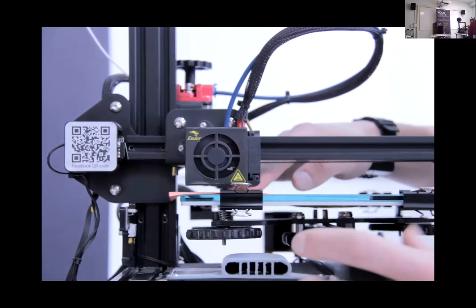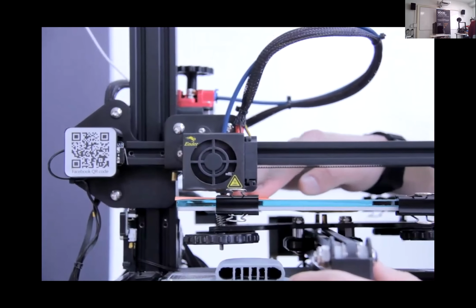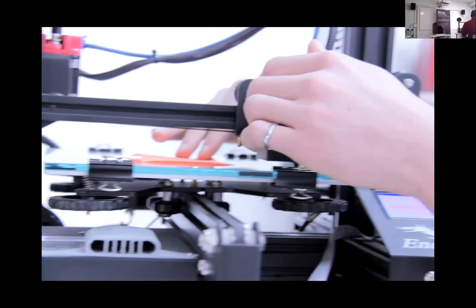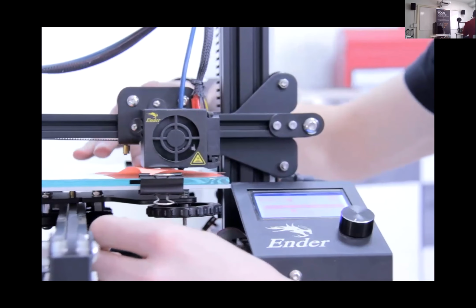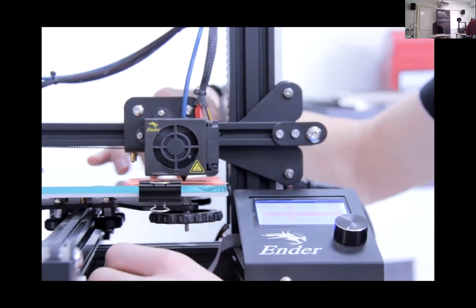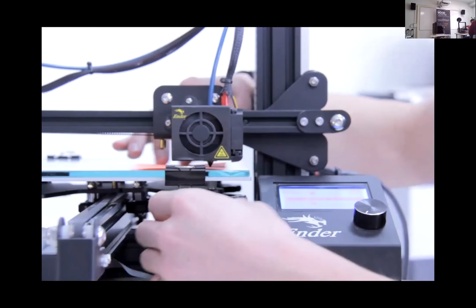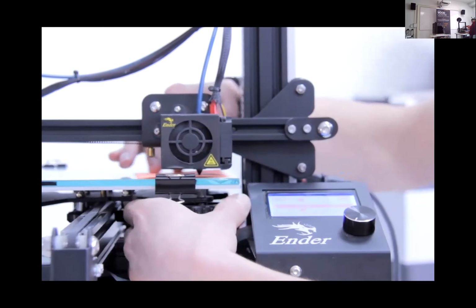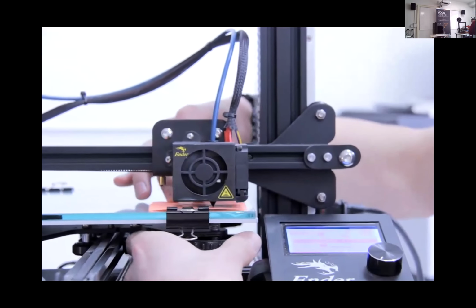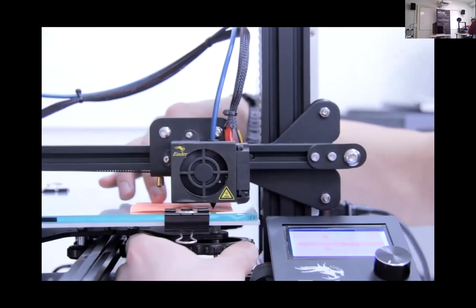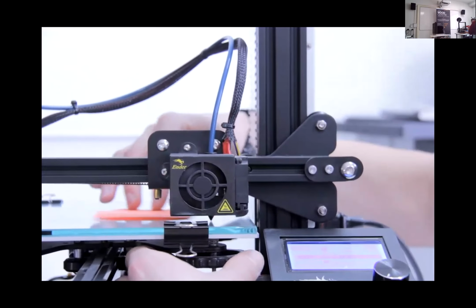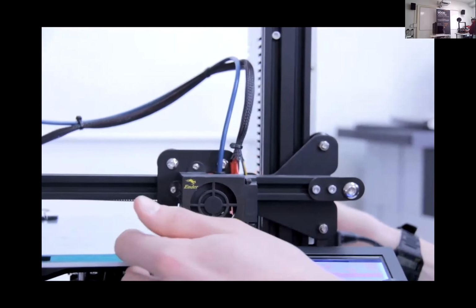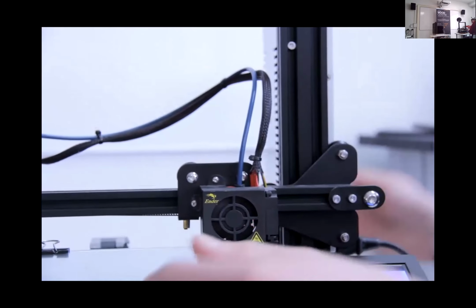and adjust it until I get a nice paper's width off the print bed. Now I can manually move the hot end to the next corner and do the exact same thing. So this one, I'm not feeling much resistance from the paper, so I better use this knob and raise the print bed a bit until I start feeling some resistance. So there we go. So you want to do that in each corner. So all 4 corners. You want to do the same thing here.